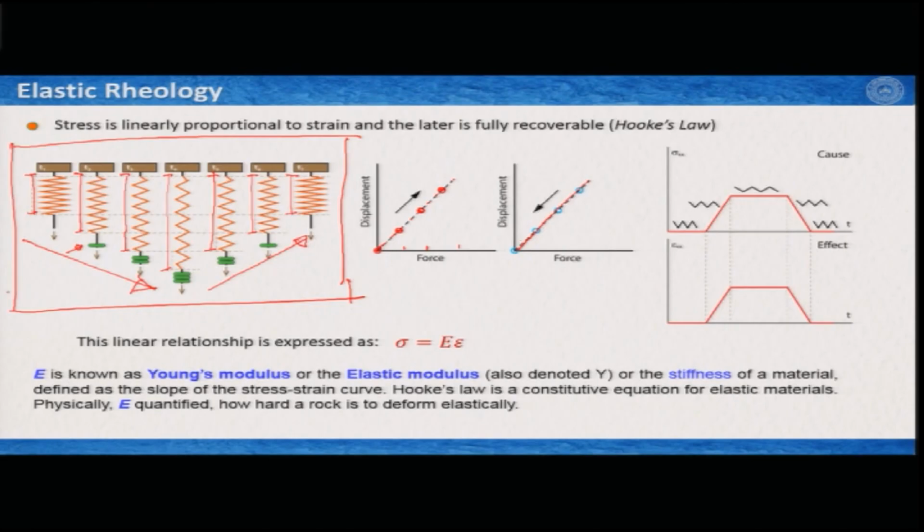We can also visualize this in a different plot, what is given here. In one plot we have stress versus time, in another plot we have strain versus time. This strain you can visualize in terms of elongation. So, till this point it was T1, where we did not have any load, any stress, and the strain was also 0. Then we slowly started applying the load with these green bars, and we see the strain, or elongation, also increased.